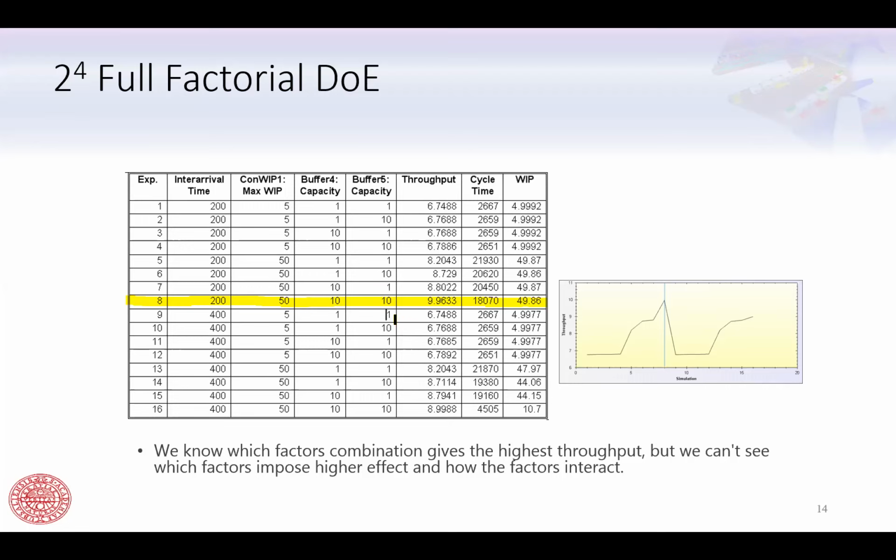And the interesting information is if you compare with another setting, which has only one small difference, you will see that it is quite contrary to people's understanding in industry. If you have a cycle time problem, a cycle time bottleneck, then you find that it's not only the buffer in front of, upstream of, the bottleneck station that is important. You find that there is a quite significant difference. But then, of course, in this case, if we only bother about the throughput, then we have a single objective. So you find a peak there.